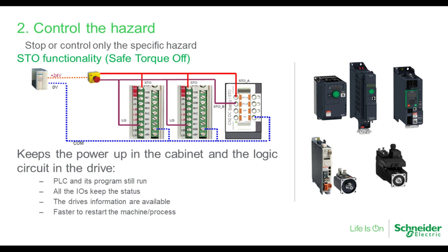Another thing about that is that a lot of products have that kind of technology built right into them. So AC drives for controlling asynchronous motors, as well as servo motors and robotics controllers, are already doing a very good job of being precise in their control of the motors. And because of improved technology, the feedback from the motors and from the encoders, for example, and position sensing devices is able to be tested and certified to such a degree that those motor and motion controllers can actually handle safety functions directly on them. So that's something that can save money.